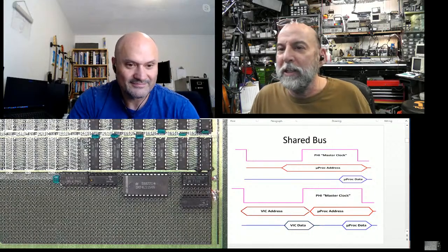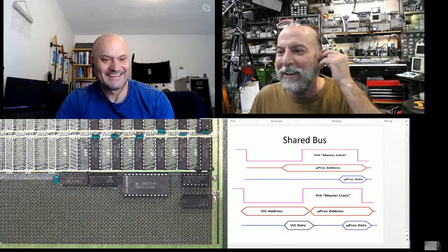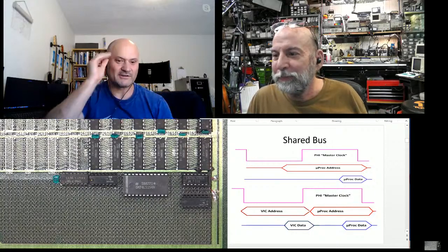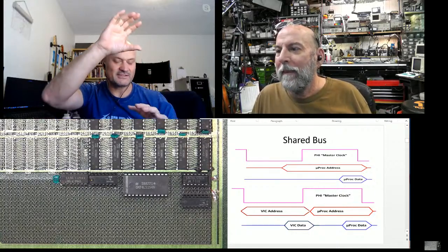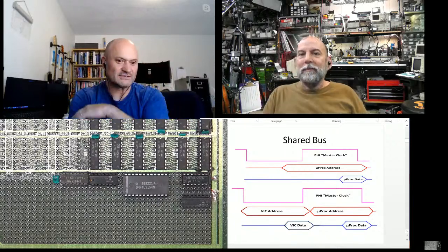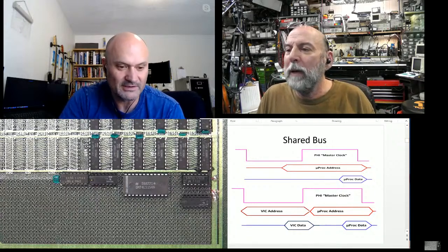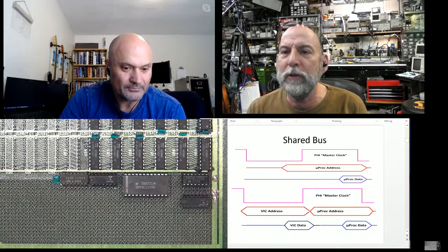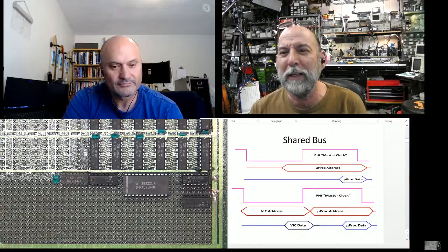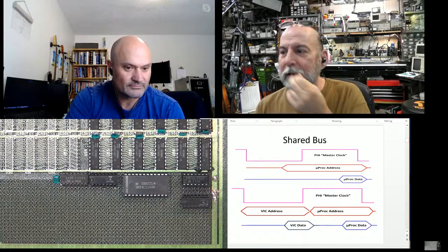And so for some reason, I thought I needed more than 3 to 8. So obviously I decode the heck out of some. Yeah. So these are used on the address bus to divide the top address bits to get different sections of memory for either I/O mapping or what have you. And even memory selection, because the memory, these are two 114s. They're probably 1K by 4s. I forget. They're probably not bigger than that. So I would have needed to select banks of 1K.